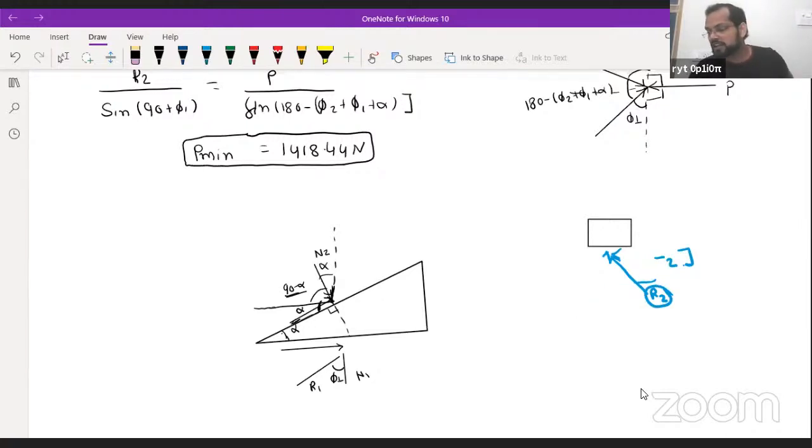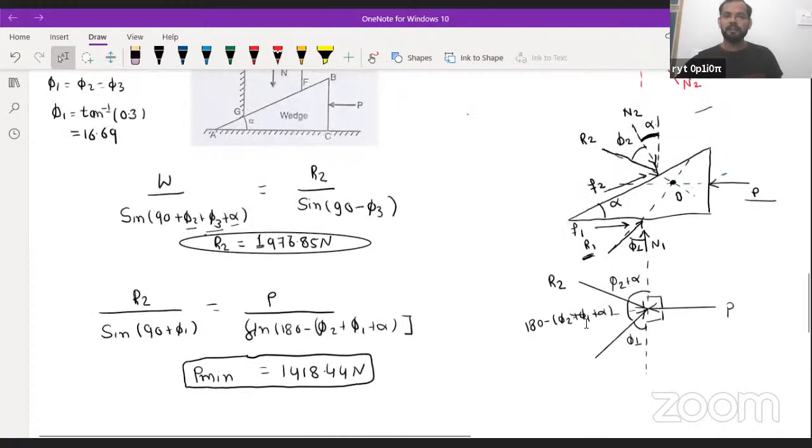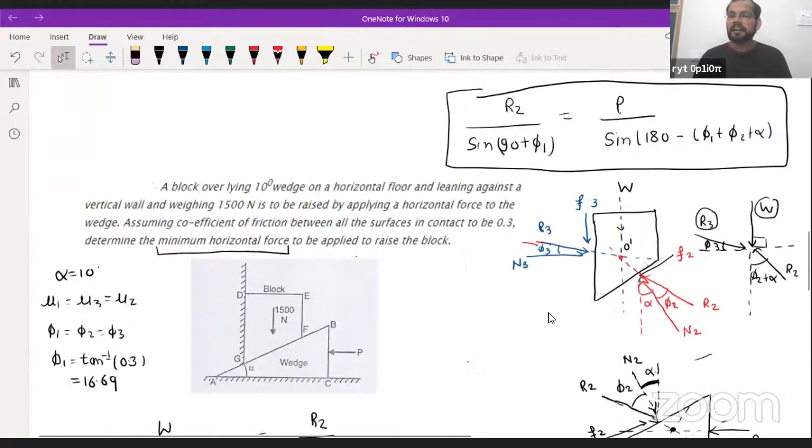And what about the reaction force applied by the wall? The same thing is happening with the wall. Prince, you can see here that in this condition, I considered the normal reaction due to the wall and friction force. Why friction force? Because when the block is trying to move upward, the surface is rough, so the friction force will act downward. In this condition, the resultant of these two forces will be R3. That's why I consider R3 here. R3 will produce the same effect as that produced by F3 and N3. Is there any problem? Fine.